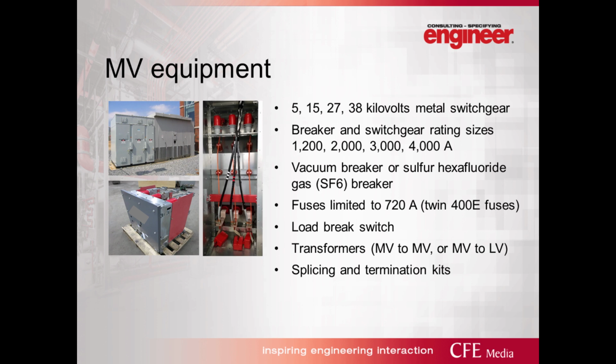And then in every medium voltage system, eventually it has to get transformed down to lower voltage for utilization. So typically you would see a cast coil or dry type transformer for indoor or an oil filled for outdoor. If you look at the picture at the top on the left, this is actually a case where they used a cast coil transformer outdoors. And also in that picture, you'll see the two load break switches on the primary side. This provides the protection and isolation for that transformer. So they're the medium voltage switches on the primary side of the transformer.